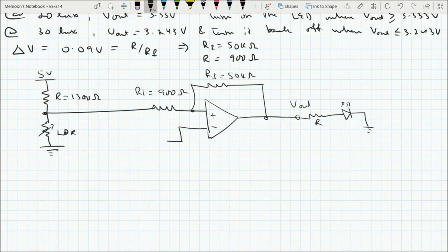So the solution to our problem is almost complete, and here we need a Vref equal to 3.33 volts, but the remaining point is that we have to provide this 3.33 reference voltage using a digital to analog converter. So this means that we have to connect it through a DAC.